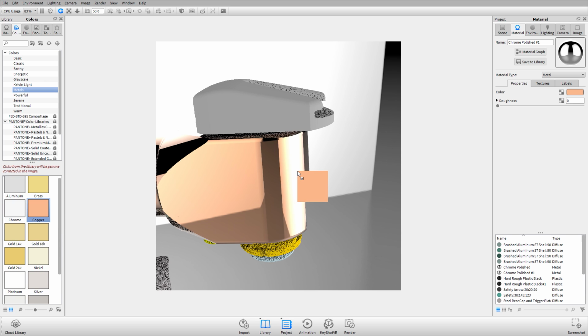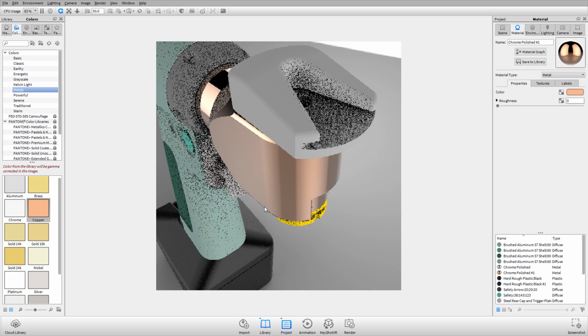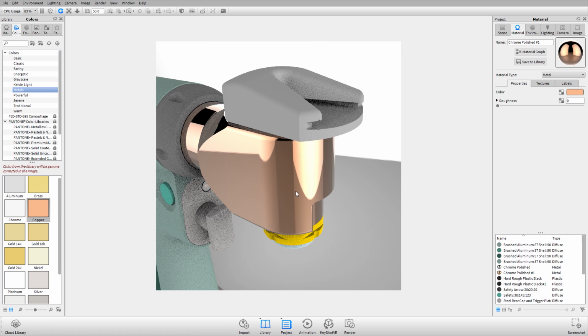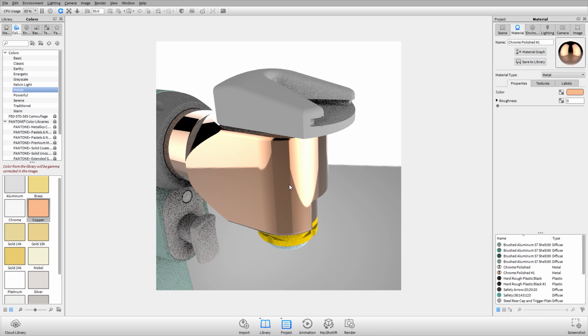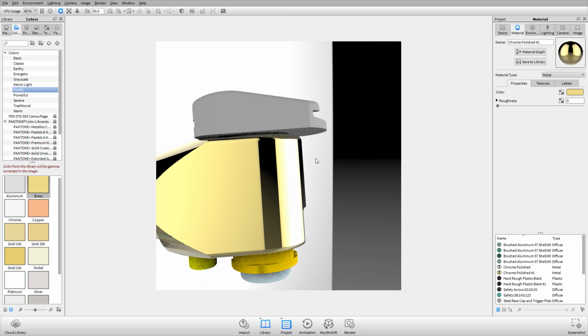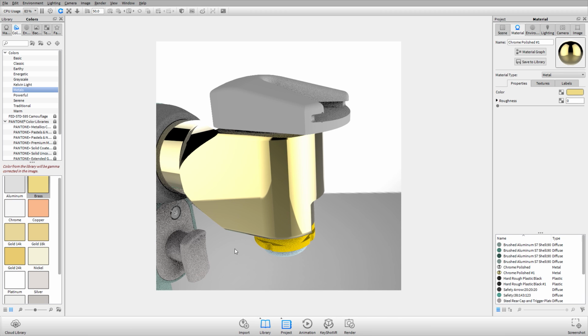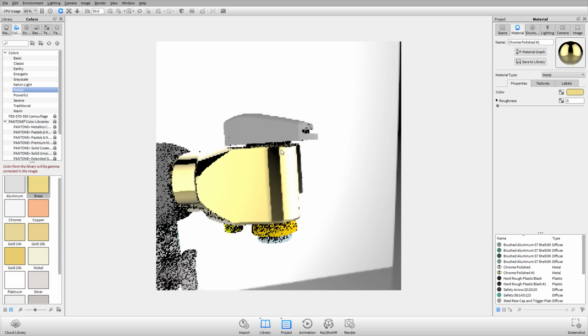And if I drag copper onto my material, that's going to look like copper because it's changing the specular color or the color of the reflection. So any light that hits this material is going to be tinted by copper. If I wanted to replicate brass, I've got a different color, and my reflections are going to be tinted by those specular highlights or those really sharp reflections.